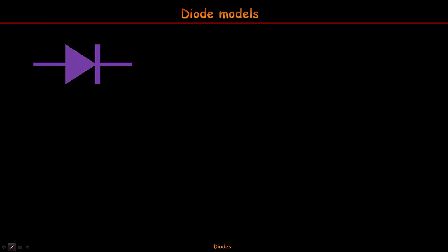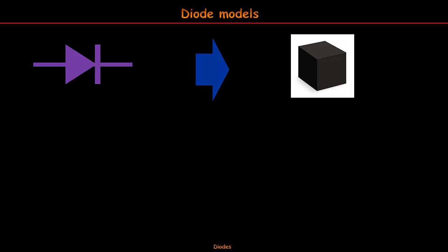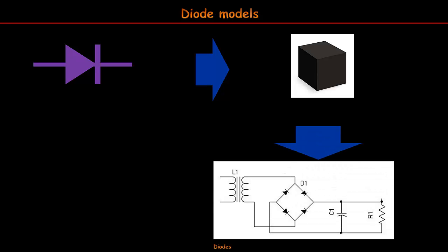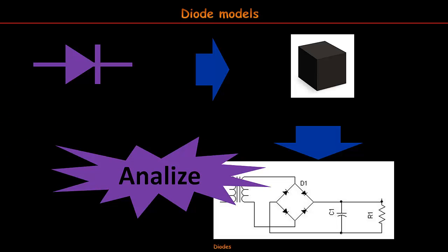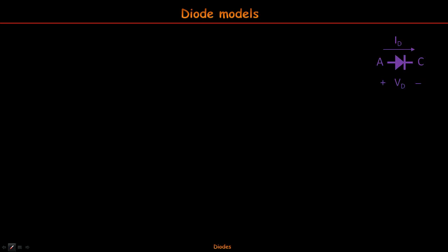When using the diodes in circuit analysis, using the exponential equation would lead us to transcendental equations and a big mathematical mess of numerical methods. We will use a model instead, a circuit that can model what is happening in the junction, and thus use it as a black box to analyze what is happening in the rest of the circuit. Using the model of a diode means replacing it with a schematic circuit that behaves exactly as the diode will do in the circuit, at least as an approach. Then we will make approximations to the actual characteristics.